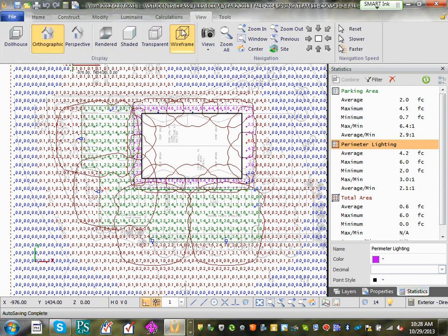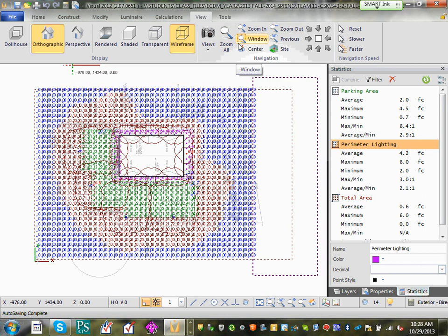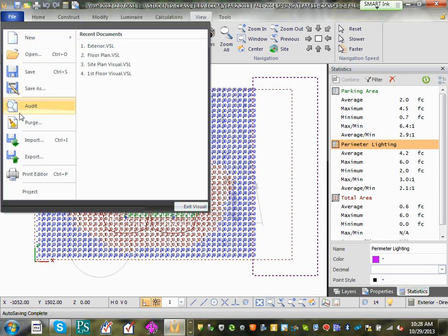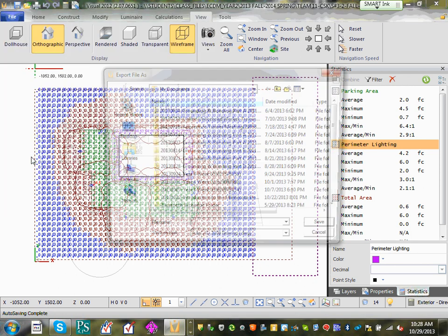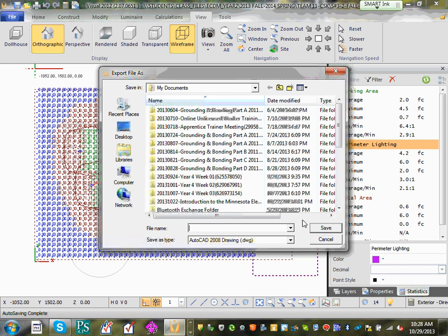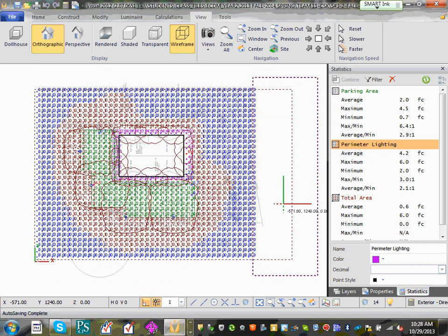So if you go to this one, that's where we did the export. And that might not be a bad idea because you already have your own title blocks, and you bring this into the model space and work on it from there. Yeah, so file export out of here, and it'll generate a CAD file for you. That's at the end, guys, when we're done, we will export this into CAD, turn everything off, leave the layout on the fixtures, import it into Revit, drop our fixtures in Revit, circuit, switch, and tag. Done. You can see how the two softwares mesh together.